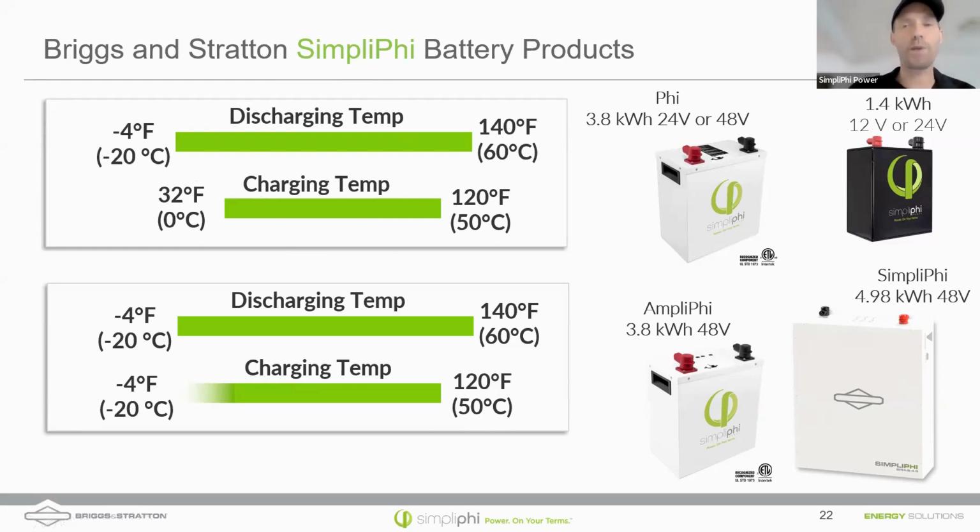If you just put your battery inside of an enclosure, as a battery charges and discharges it gives off some heat, so that'll help insulate your battery. And ideally you could just install these batteries inside. If you're installing them inside, you don't have to worry about the temperature range as much because typically internal temperatures are slightly regulated by the household.